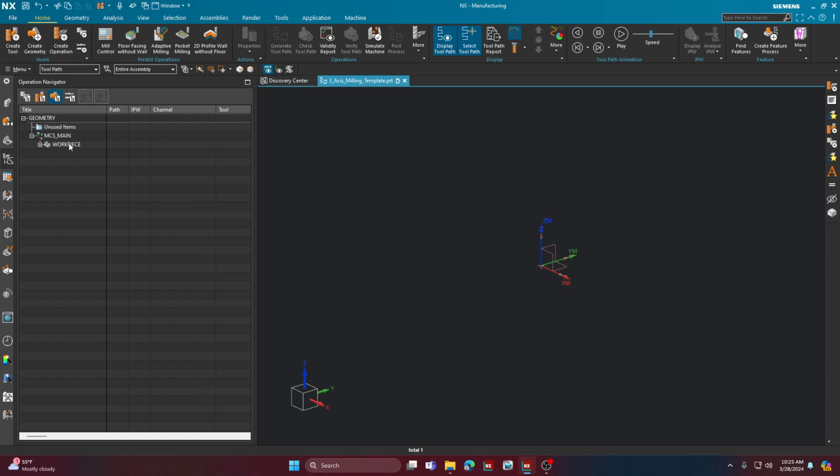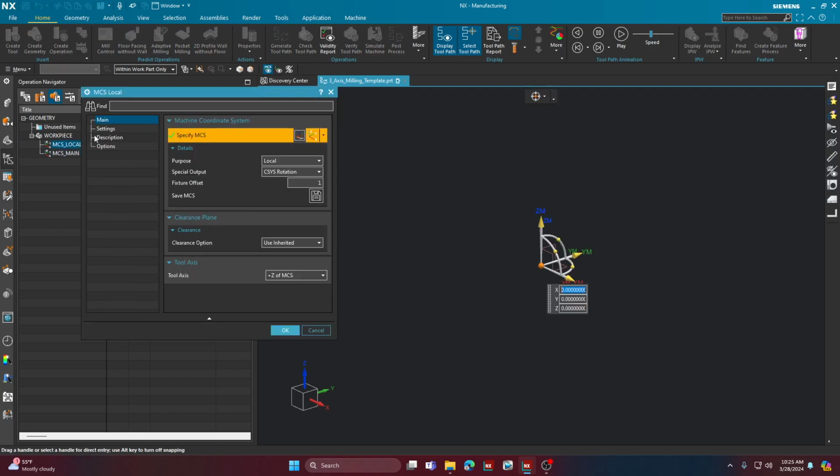And let's say that for the purposes of this example, the workpiece winds up being the parent all the time, and of course, we have 2 MCSs, one for G54 and one for G55, right? I've got to flip the part over and mill it out. Okay, if that's the case, all I have to do is rearrange this, and of course, I will rename this.